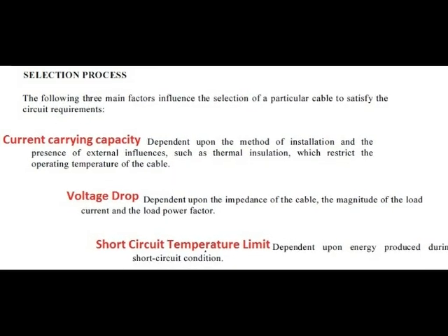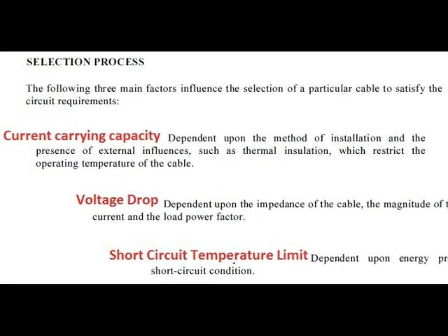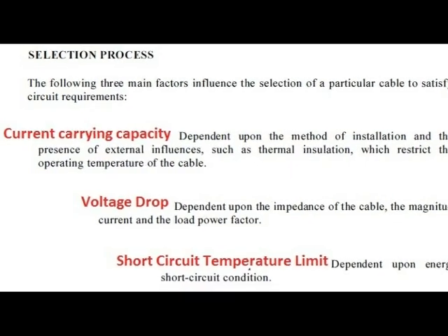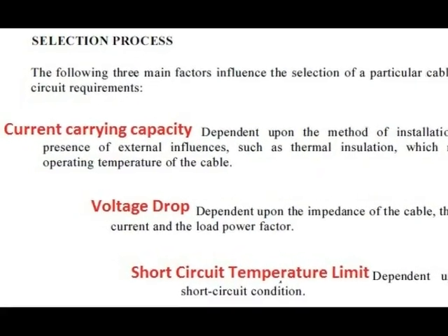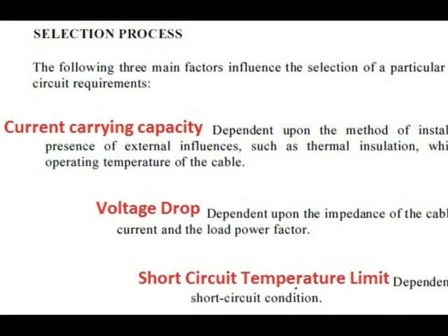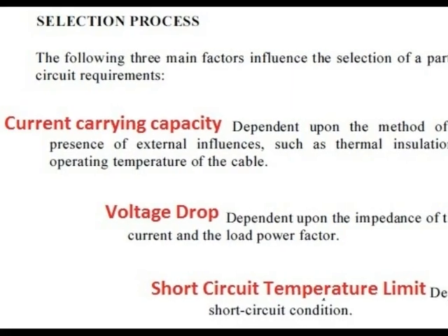The cable selection process using NZS3008 is first of all determine the current carrying capacity, then look at volt drop requirements, and thirdly short circuit temperature limit.